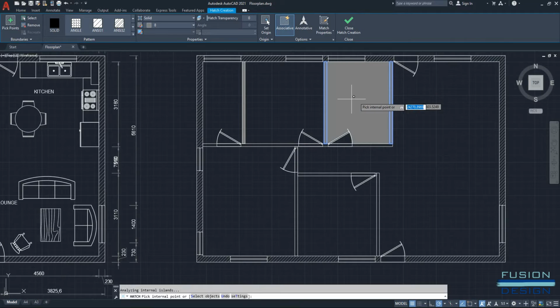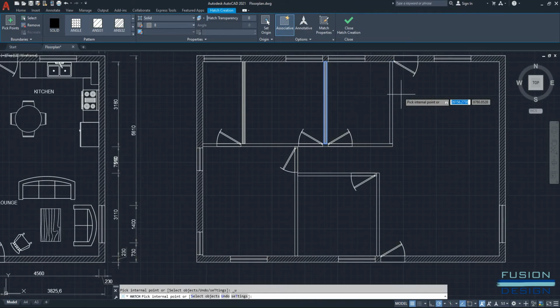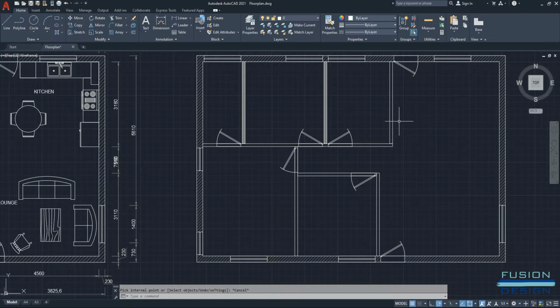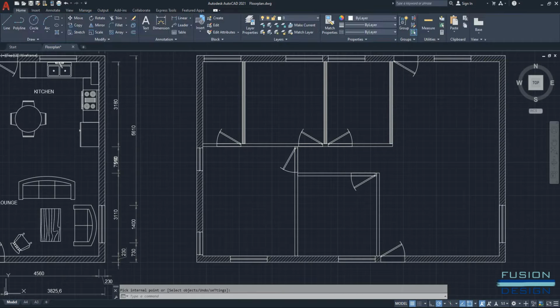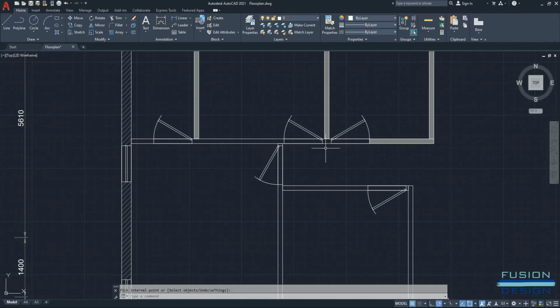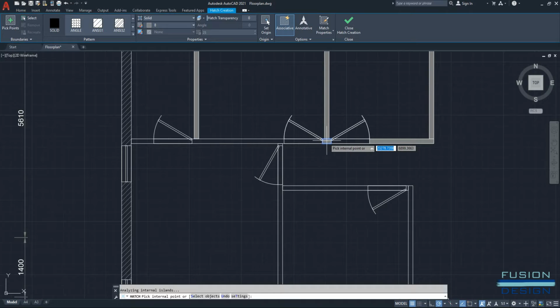If you've done what I've done now by selecting 2 walls, you can undo to deselect the last wall. So undo is a simple Control Z command if you're using Windows. Enter or spacebar and repeat this process until you have hatched the entire area's walls. Don't hatch the door openings, only the spaces in between.